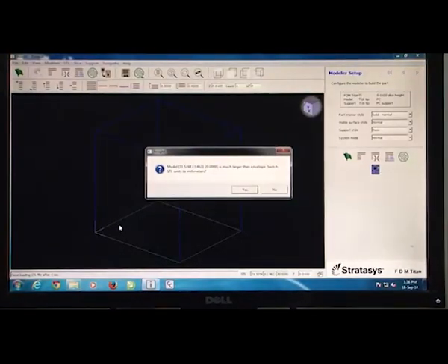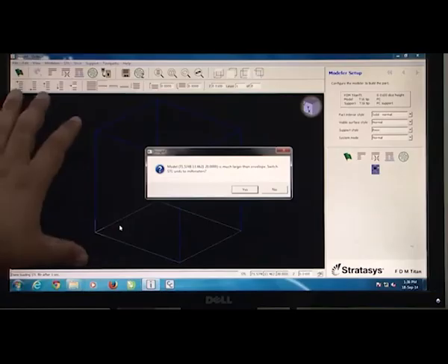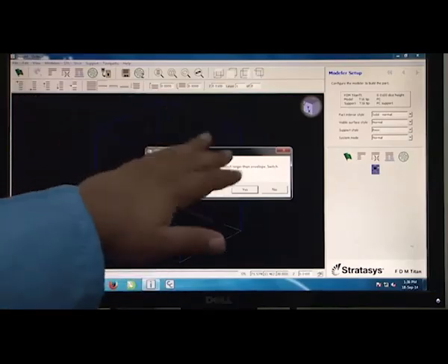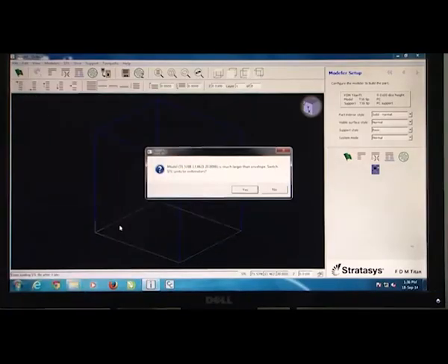So, it is not scaled, we have to scale it because there is typically a confinement volume which would be defined by the bed size of the stage. I think I had mentioned it earlier that the bed size in the case of FDM Titan is about close to 16 inches times 12 inches times 14 inches. So, that is about the size of the biggest part that can be accommodated within this particular system. And I also defined that the minimum layer size that this system is able to resolve is about 125 microns.